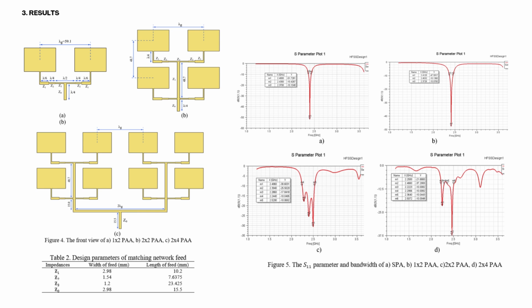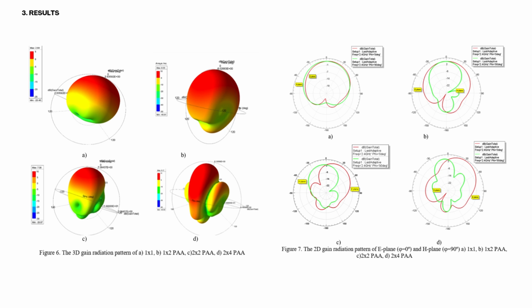The next parameter is the antenna gain. The antenna gain is one of the most significant key components to describe how the radiation pattern of the antenna is concentrated, and combines the directivity and the efficiency of the antenna into one easy-to-use parameter. In order to see the full picture of the received data, we use the radiation pattern extracted through far-field analysis in Ansys HFSS.